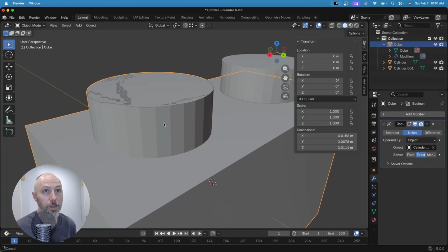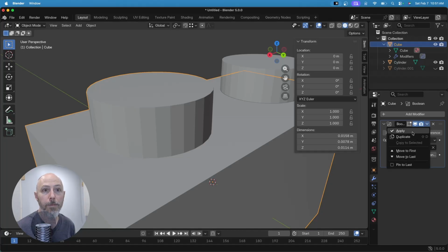There is my cylinder, but if I hide my cylinder, there's also now a second copy of the geometry from my cylinder in this other object. That's because the union modifier, see it says right here, combine meshes in an additive way. It's going to take all of the geometry of the two meshes and put them together into one continuous solid piece. So that's actually what we want to do here. So I'm going to go ahead and apply that.